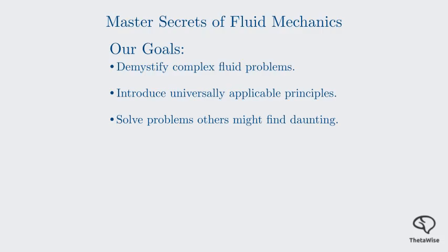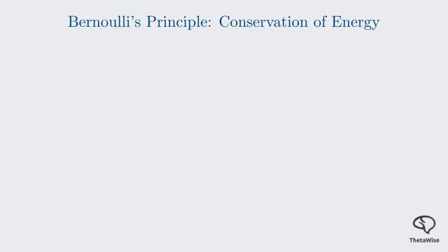Let's get started. Our first big idea is to think of a problem not as what is the answer, but as how is the energy moving and changing. This is the foundation of the first law of thermodynamics. And in fluids, it's expressed by the famous Bernoulli's equation. Bernoulli's principle states that for an incompressible, inviscid, steady flow, a change in velocity causes a change in pressure. More generally, it describes the conservation of energy.